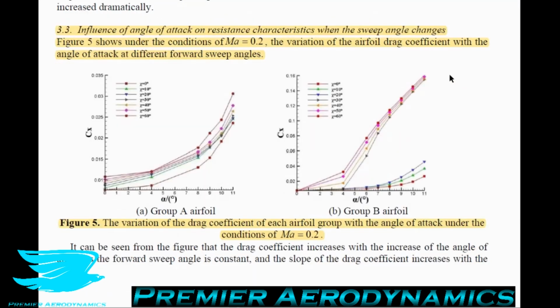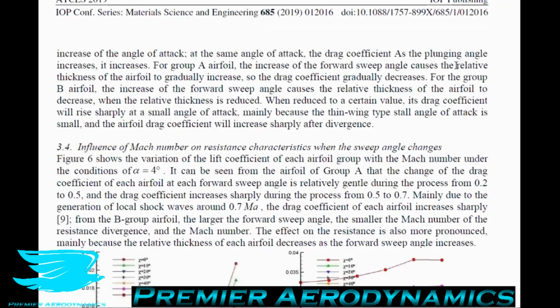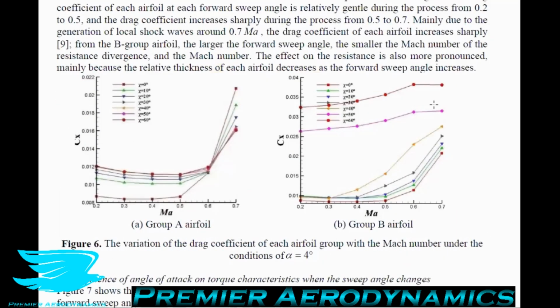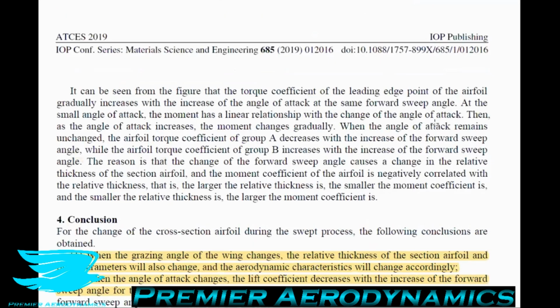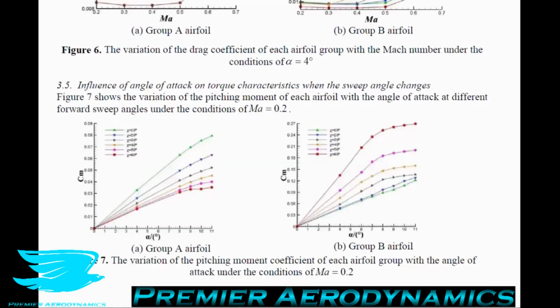You want to keep the sweep angle low in this particular case. So finally, we're going to talk about the pitching moment. And this is very important because the pitching moment affects dramatically the stability of the aircraft. The pitching moment is the tendency for an object to either pitch forward or backwards.